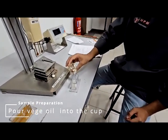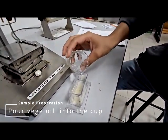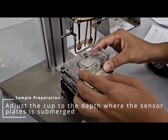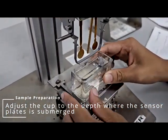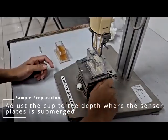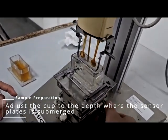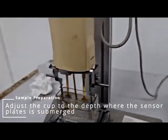The first step is to pour the vegetable oil into the cup. Next, attach the cup on the table by the guide and adjust the cup to the depth where the sensor and plate are submerged. The table is lifted using the knob until the vegetable oil is at the same level with the necking on the sensor plate.